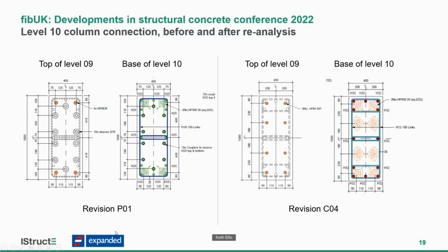Our first revision, P01, included 4 shoes in the corners. That enabled us to put the columns up propless and quickly. But in addition to that, we needed 10 dowels through well voids, and this is what drove that reanalysis really, trying to get these additional 10 well voids through. That image we saw just now was pretty much impossible.